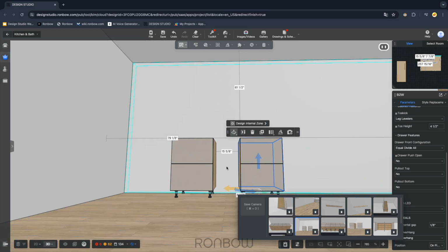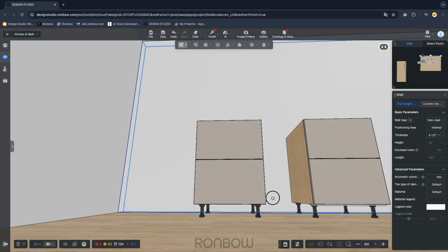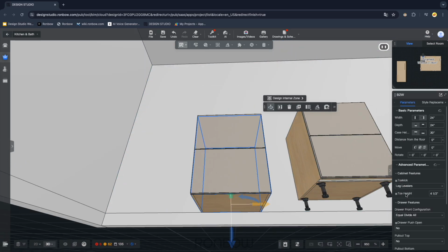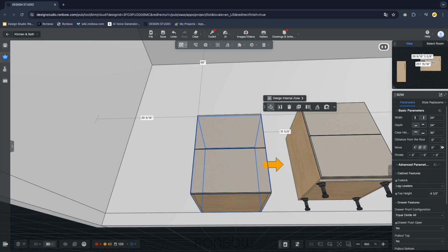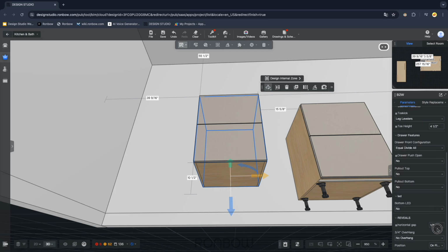Now, for the second option, it appears only if your cabinets do not have leg levelers. To remove leg levelers, go into the parameter list and select No Base under the toe kick option. Then add 10.5 inches to distance to floor, since this option is used for floating or vanity cabinets. Now, when we look at our bottom LED, a new option called Routed Recessed LED will appear.